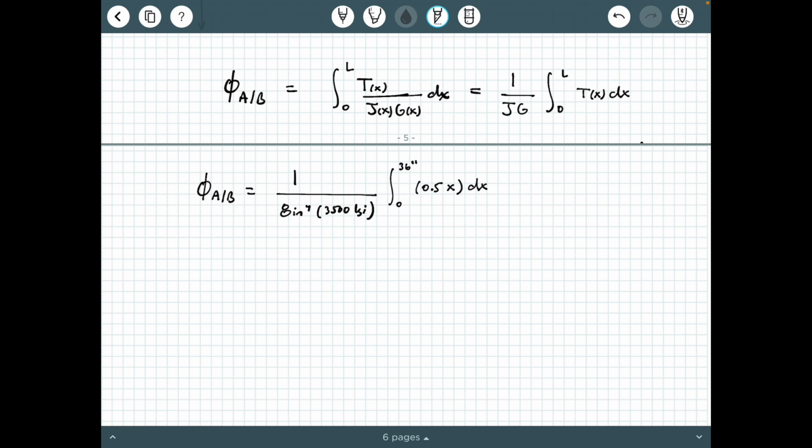But the feet, the kip feet, is being represented by this x, and when you multiply it by the equivalent of L, which we're doing by integrating with dx here, that's going to incorporate the TL together in the numerator. Converting that 3 feet to 36 inches incorporates that conversion factor of 12 inches by putting it in this upper limit, and so it gets inserted into this x during the integration process.